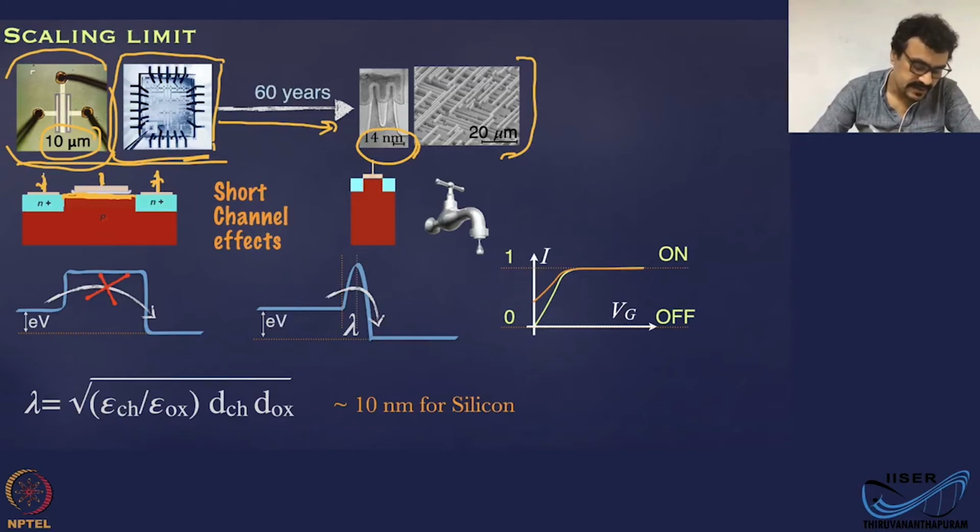So we can visualize this the following way. You have some kind of energy landscape where you apply a small voltage, that is eV, which is mentioned here. Though we have applied a small voltage, you won't get any current through this device, because there is no conducting channel in the middle, which you can visualize as a barrier for the current.